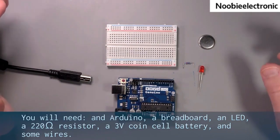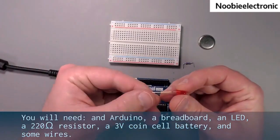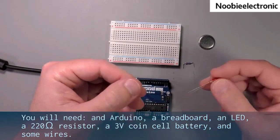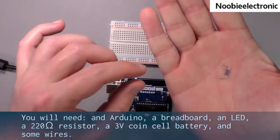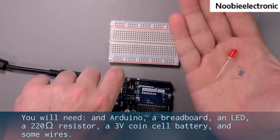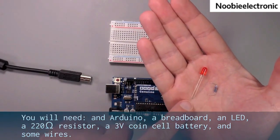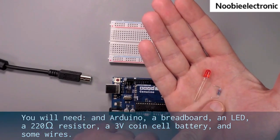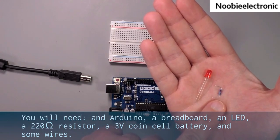To follow along, you will need, of course, a breadboard and your Arduino. You'll need an LED, a 5mm LED will do just fine, and you will need a resistor. The purpose of the resistor is to protect the LED from burning out. Because the LED internally only has very little resistance, it is possible to get a lot of current flowing through it if that current is not going first through what's called a current limiting resistor.